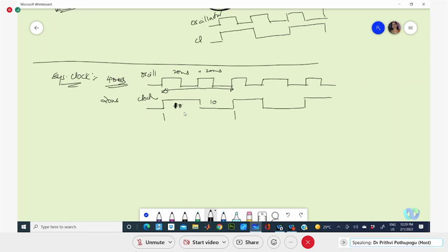Now, this is an automatically generated system clock. The same system clock in the same design, you can operate that manually also. Manually, you can generate different pulsed clocks. If it is automated, it will have equal on-off duration, that is a 50% duty cycle.